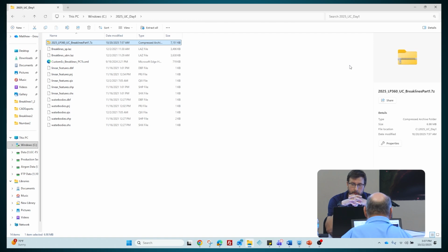As you've noticed, if any of you have been looking at laser scanner data, a lot of times there's a thickness to it, and you can peer through the vegetation and different features. You've got different features in the data set, so you don't necessarily want to focus on just the surface. Sometimes you want the minimum value in that spread of data, or the maximum value. It just depends on the context for what you're trying to do. So we're going to go over some of those conflation types and why we would use those different types.